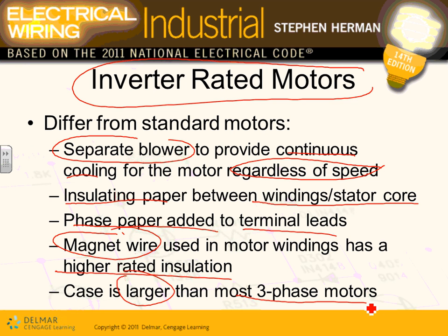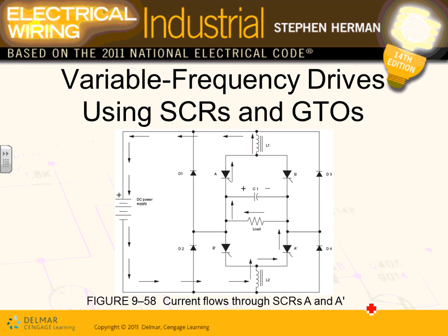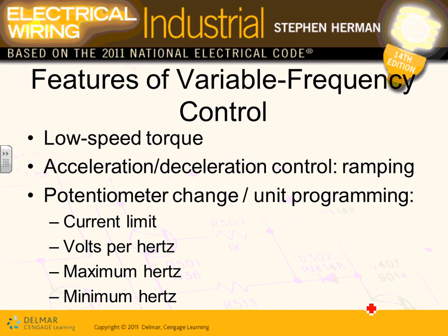When you have a VFD and you talk to your mechanical engineers, the mechanical engineers are smart enough now to ask the manufacturer to specify a so-called inverter-rated motor. So a specially designed motor, fatter, fluffier, more insulation, more cooling, so it can handle all this heat generated by the VFD. Anyway, so that's basically the motor.